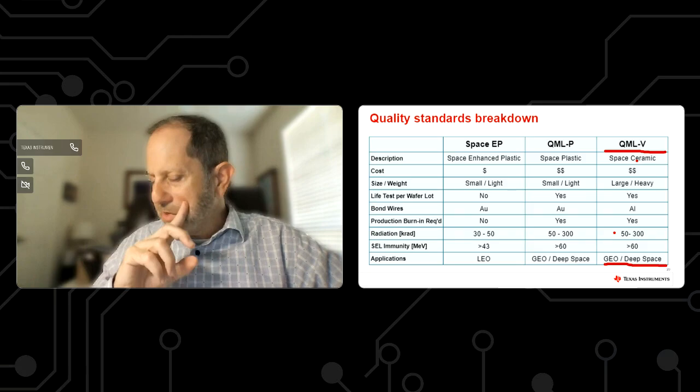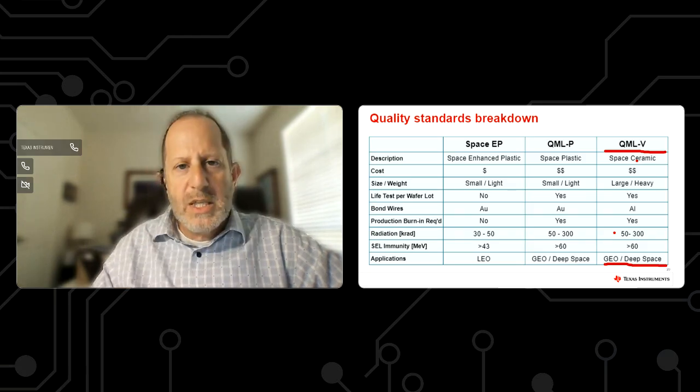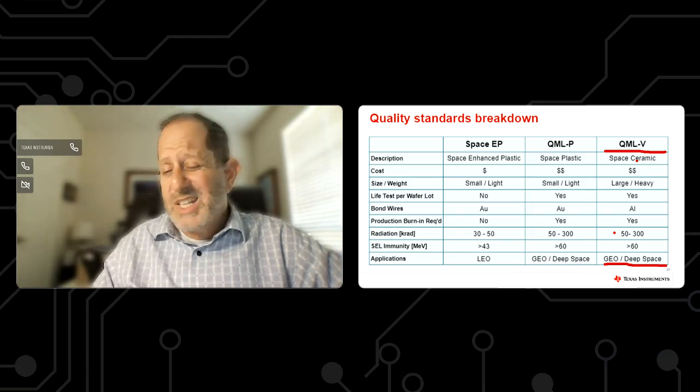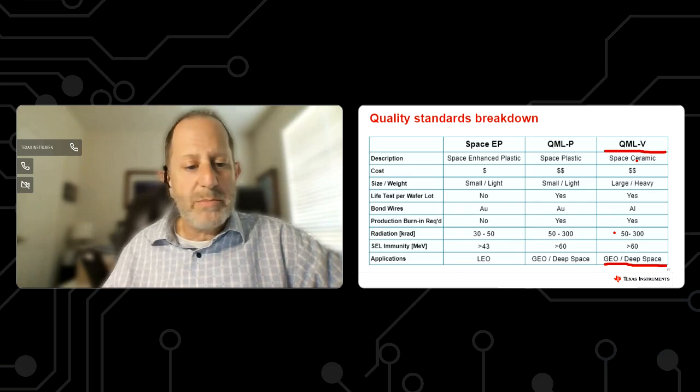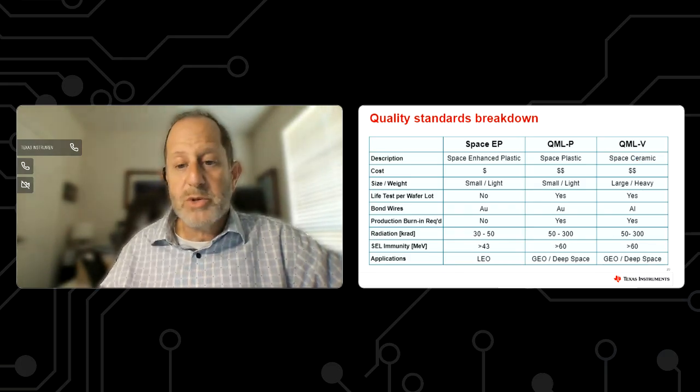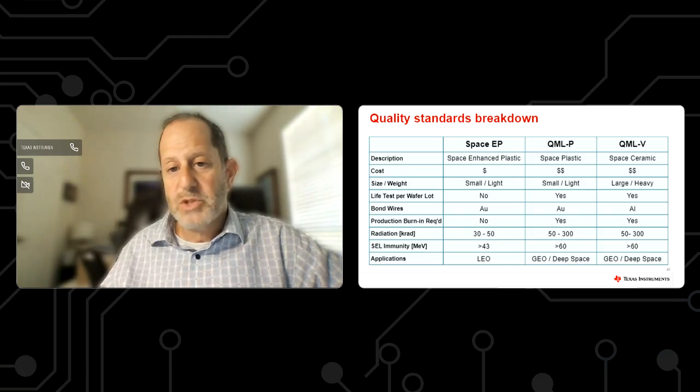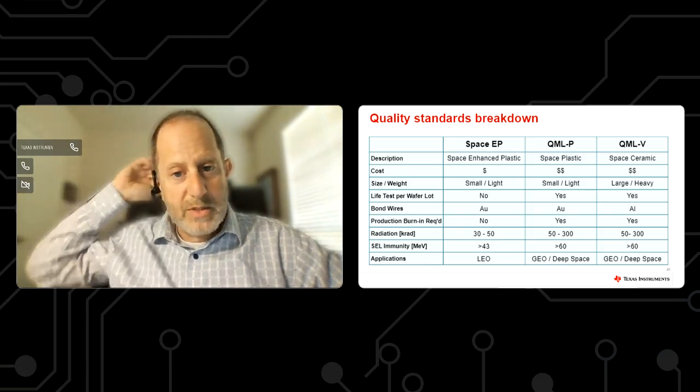But there has been a shift and a trend in this market space as the space applications have grown. The ceramics are big, the ceramics are heavy, they're physically big, which means when you're trying to deal with high frequency and things for RF purposes, we don't like big. We like small and tight and concise. And all the parasitics associated with a big, physical package tend to hurt things as we start pushing into the higher frequencies. And as we mentioned, we're trying to do that more and more with these systems.